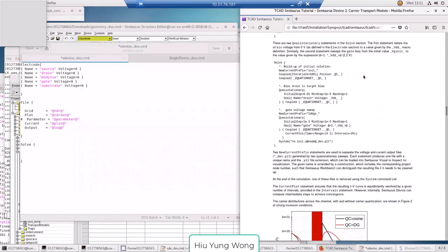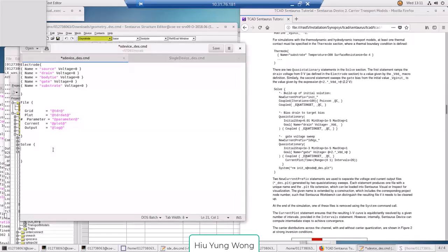So now I'm also going to try an example. What do I want to do, right? The first thing I'm going to do is type this, couple, right? You just type with me, iterations. Look at this. This is not a curly brace. This is the curved one, right? Equal to 100. And then I'm going to type Poisson. What does it mean? It means that at the beginning, please solve the Poisson equation only.